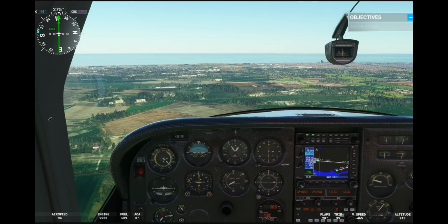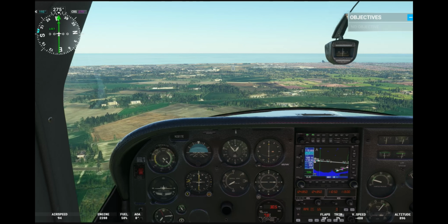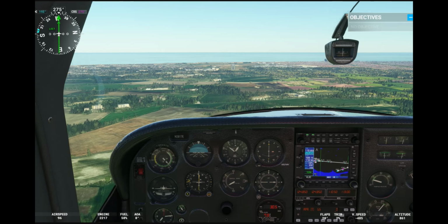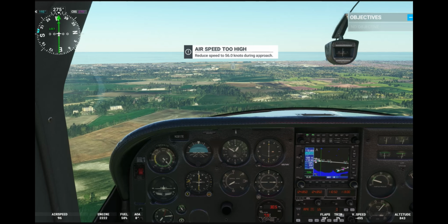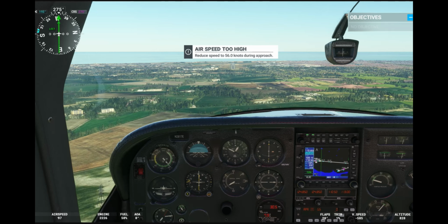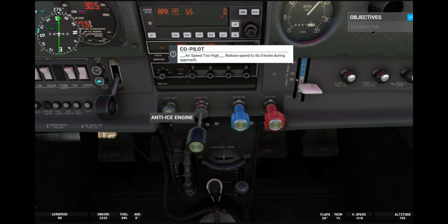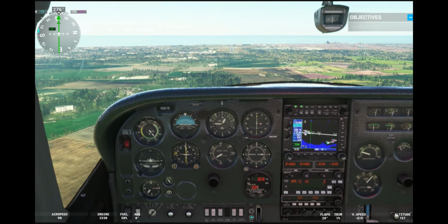per minute. Pre-landing checks are brakes off and functioning, gear down and locked, flaps are set, fuel pump is on and not set on the auxiliary, altimeter is on QFE, radio is on the correct frequency, and we are cleared to land. The correct runway.